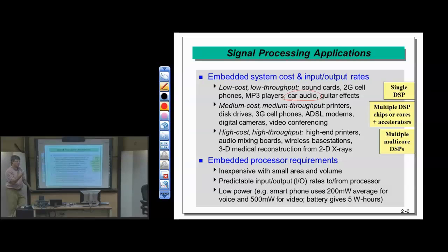And then you have floating point, which allows you to scale, with 8 bits of exponent, dramatically the number that you represent. It's more than just the 24 bits of mantissa. Now you can represent very loud and very soft sounds because of the floating point format. So it's ideal. And there's a paper in the reader on the use of the C6700 family, floating point 32-bit family for audio applications. In your reader, there's an article by Gene Franz and Ray Seymour on this, both from Texas Instruments.